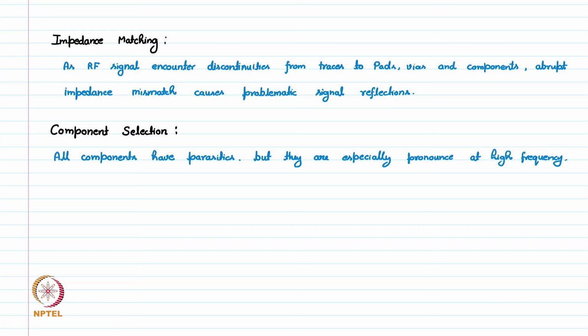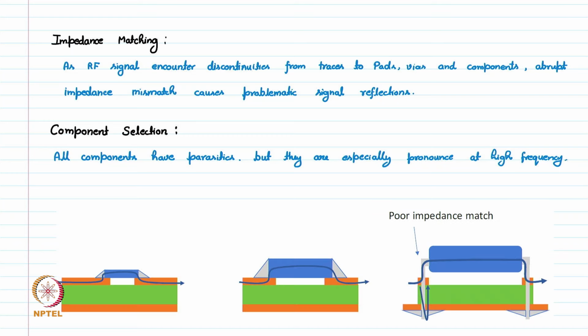So for example, we have a 100 ohm resistance to put in the PCB, and now our frequency of operation is very high, and we have multiple options of putting this 100 ohm on PCB. One is, let's say, this case on the extreme right. This is a resistance which is a through hole component. Through hole component is something like this.